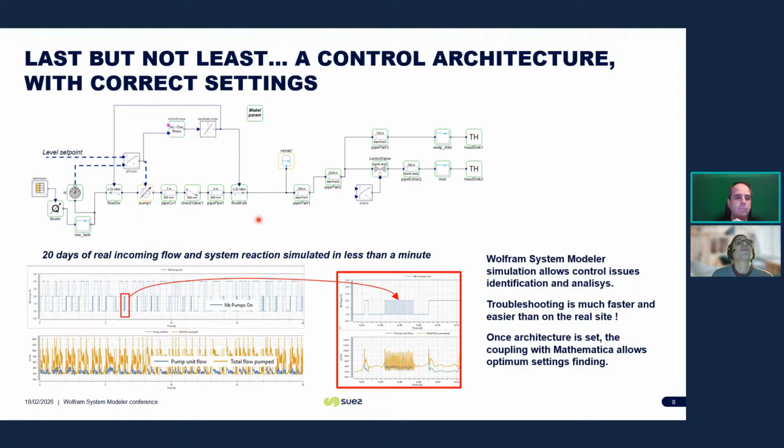Thank you, Pedro. So to complete our system, obviously we need a control, and for this system, the basic thing, we want to keep the load tank at more or less constant level. We don't want it to overflow on the roads, and we don't want it to be drained because we cannot pump anymore. So quite logically, we have a level set point for this tank. We have a level measure, and we feed a PI controller that accelerates or slows down the pump.